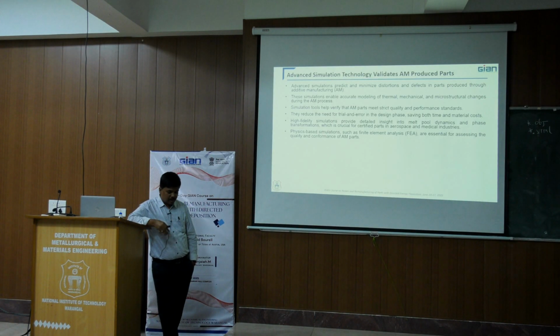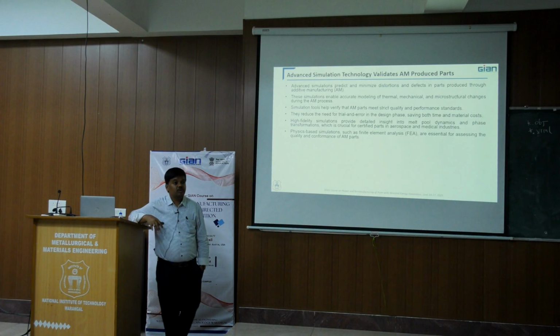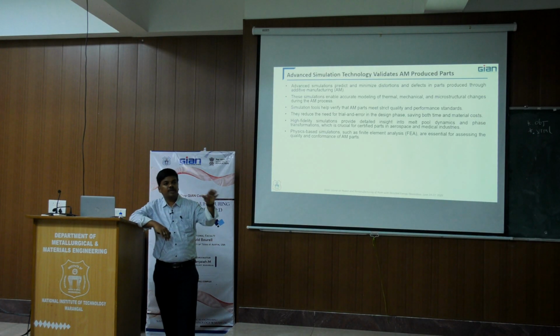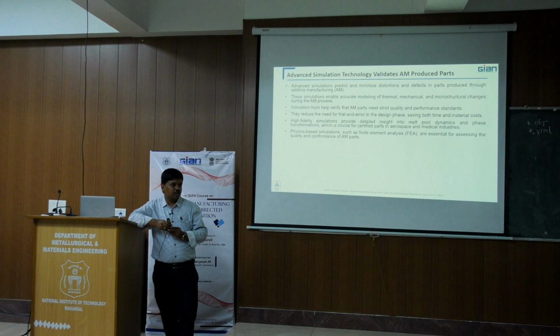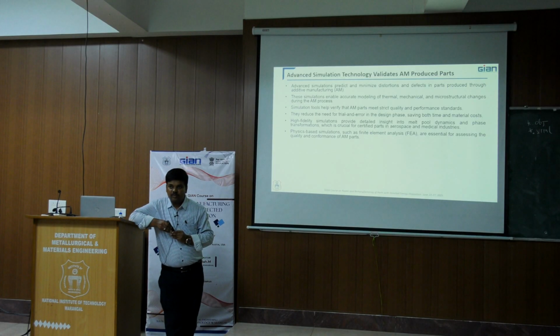Because you might be knowing, nowadays there is a lot of in situ monitoring and it can give feedback signals. In what way are they going to give the feedback signals? Machine learning can detect multiple temperatures and adjust the laser power as well as the scan speeds. Because if you want to manufacture one component, laser power and scan speed are the major important factors. That's what the process map Professor David told you about yesterday.